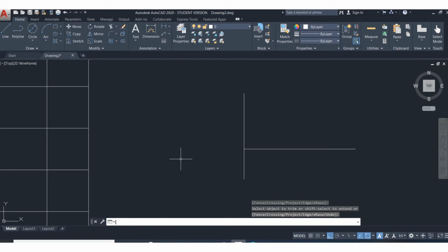So that command seems a little bit backwards, but that's the only way the software understands it. If you want to use the trim tool, you have to play along with it. Now let me show you what else you can do, which actually makes the command a lot easier to use. Instead of just choosing individual lines, you can actually draw a window around existing lines. Let me put some more lines on here. Show you what I mean.